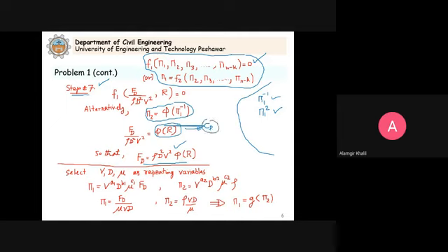And it is true. If you remember, we discussed drag forces on three-dimensional 3D bodies and 2D bodies. The graph that we drew was actually with the Reynolds number. So it is correct. It means that dimensional analysis is a very powerful tool, even though it does not provide the exact functional relationship or a 100% solution to the problem.